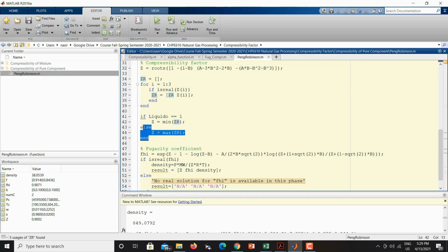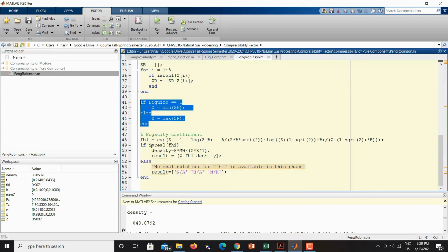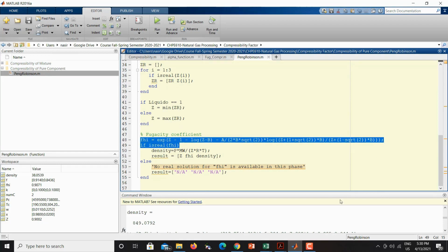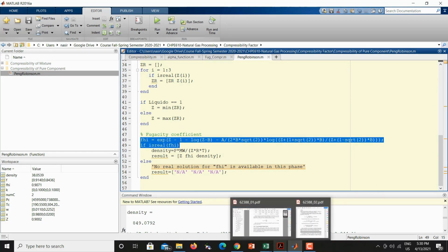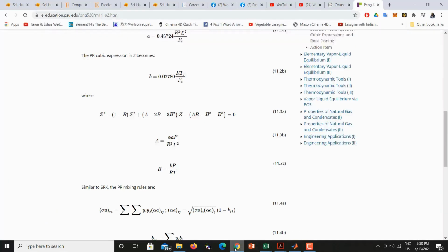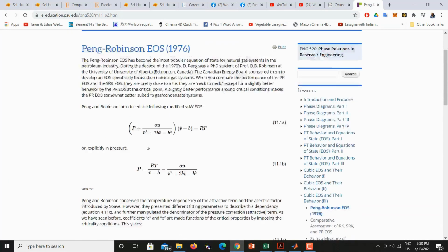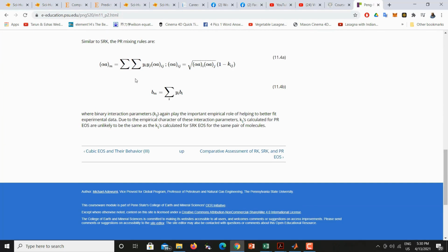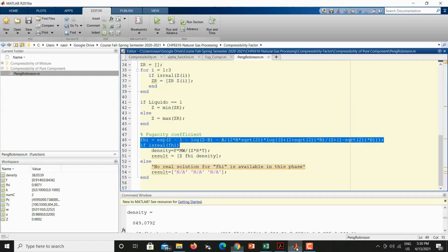Once it calculates the gas and liquid compressibility, you can use the viscosity formula. This formula is derived from the main equation. Obviously the formula is not mentioned here, but you can use it directly, and it is represented like this. All the things that you already calculated before, which require the compressibility, the capital B, the A, all of these terms we already calculated. The only thing you need is to put this formula correctly, and it will put in the values and calculate the viscosity for you.